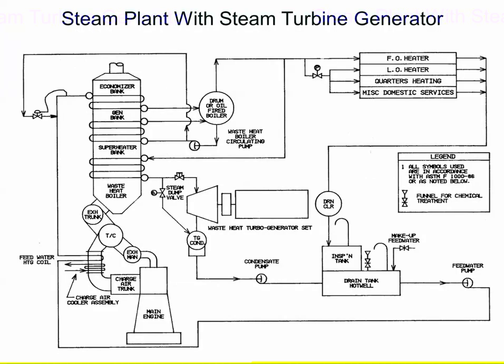Now this is an example where you're trying to pick up the maximum amount of heat recovery from the system. Here's my open feed tank. I've got feed water going through, in this case, the charge air cooler, kind of like on the Bear, where you have the two charge air coolers, one in front, one behind the other. Now I can pick up some waste heat here, and I can put that into the economizer and pick up more heat in the economizer and then into the drum.